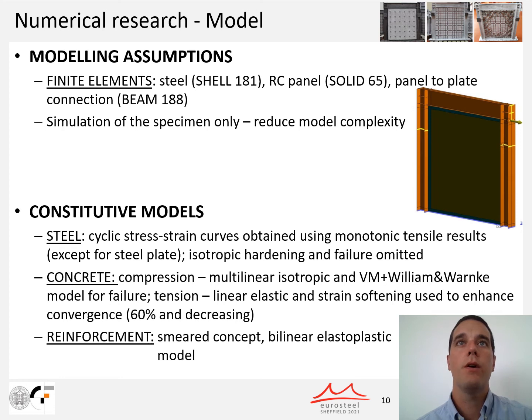As the idea was to carry out further analysis of the column flexural stiffness impact on the overall behavior of composite plate shear walls, reliable numerical models were needed. For that matter, shell elements were used for simulation of the steel parts, and solid elements served for modeling of reinforced concrete panels. The steel reinforcement was modeled using the smeared concept, and connection between steel infill plate and reinforced concrete panel was simulated using beam elements. To further reduce complexity of the finite element model, the reaction frame, out-of-plane support, truss, base plate, and rigid adapter were not simulated, but adequate boundary conditions were applied.